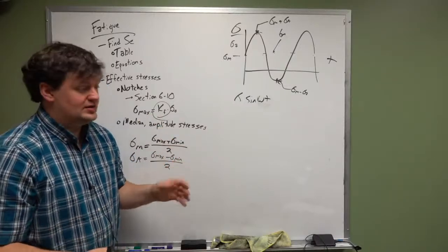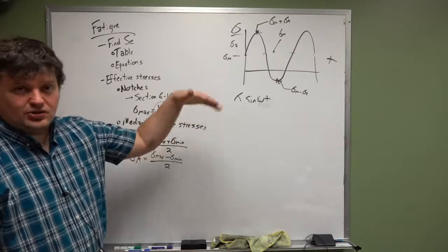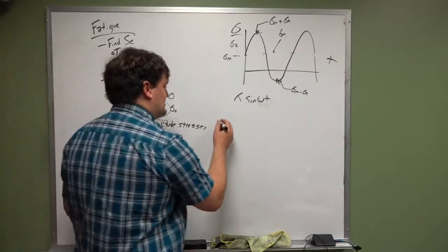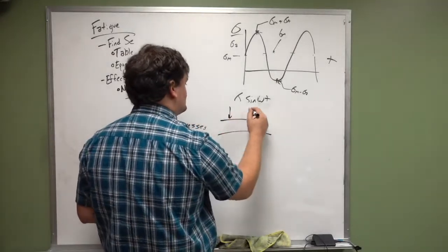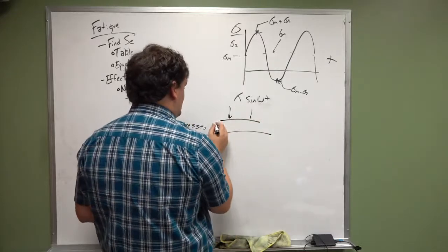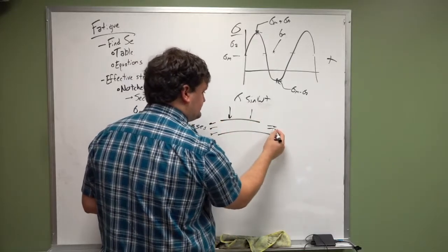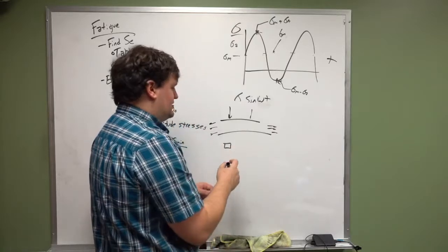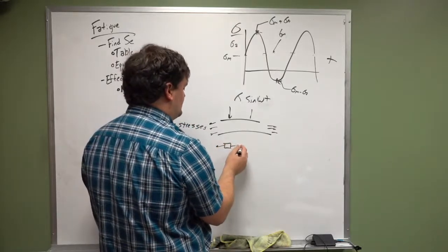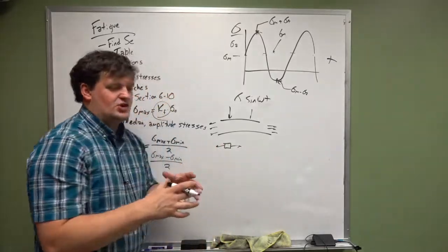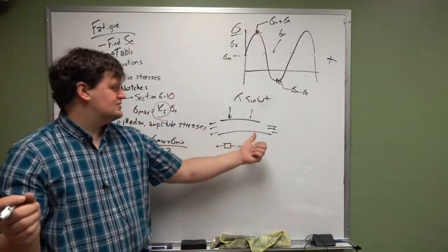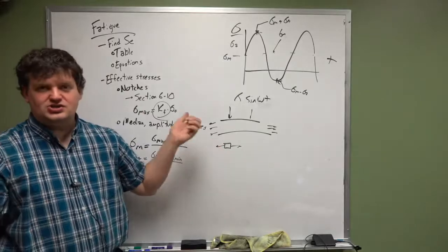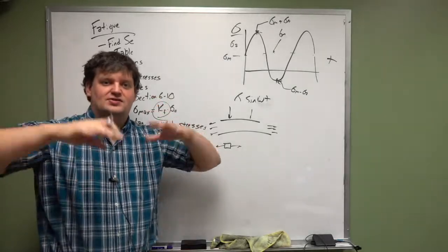That's what's needed. So if you have a cyclical loading, I'll say that this is a shaft that undergoes this shear loading, but it's also under tension, which means that your sigma X value in this direction already has some pretension because of this, but then it changes in bending stress.